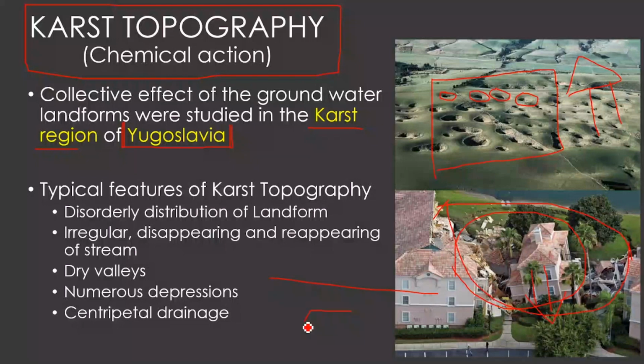Okay, and this force, the load it was transferring at this depth, it was taking it, but as time continued, the structure slowly started developing fractures, and at one point this whole system collapsed into the cavity. So these kinds of features produced by the groundwater need to be studied. We should be able to understand that these are natural features. These are not man-made features. These are natural features existing in that area.